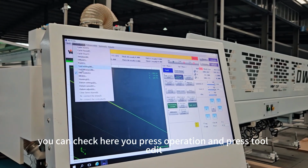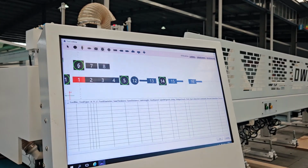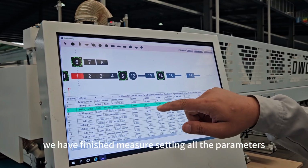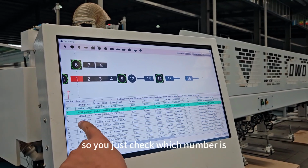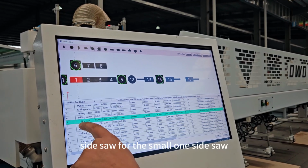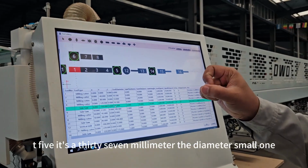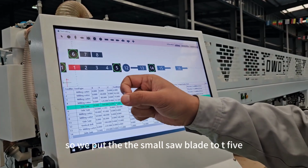So when you put the two saw blades, you can check here. You press operation and press tool edit. Because in your machine we have finished measuring and setting all the parameters. So you just check which number is side saw. For the small one, side saw T5, it's 37 millimeter diameter, small one. So we put the small saw blade to T5.